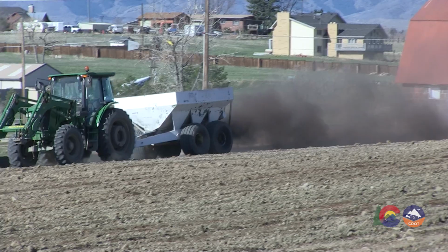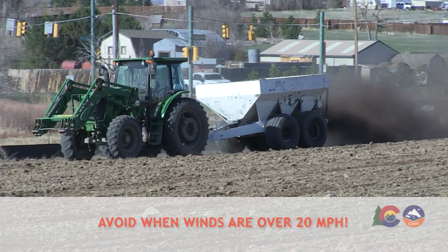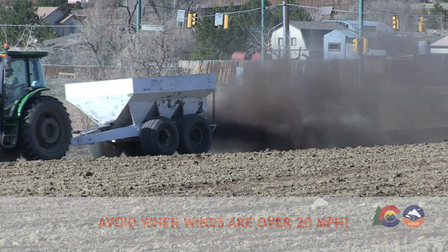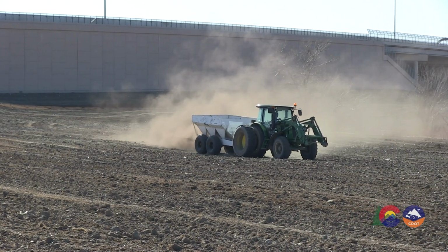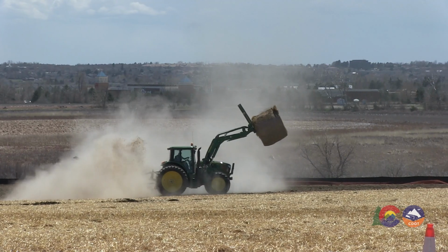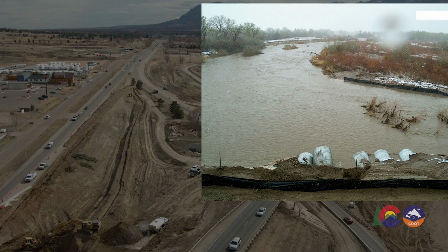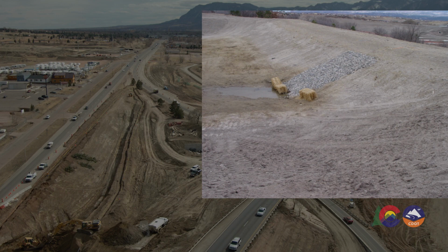What are the optimal conditions for application? Please be aware that soil amendments and seeding activities should not occur when wind speeds exceed 20 miles per hour. High winds can cause soil and amendment loss and increase air pollution, making it unsuitable for work to take place during these conditions. Also, soil amendments and seeding activities cannot be conducted when soils are too frozen or wet. Too much moisture can compromise the soil structure and create compacted soils, the opposite of what we are working to achieve.